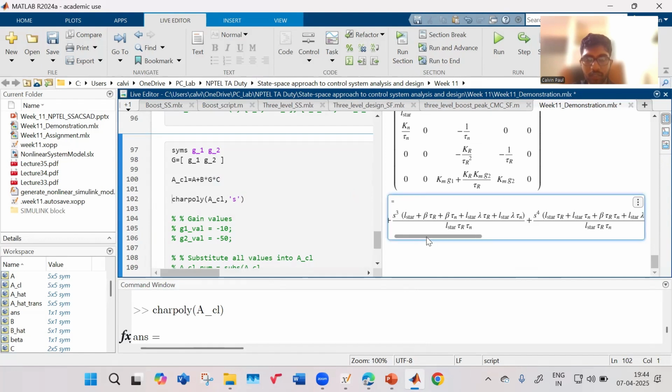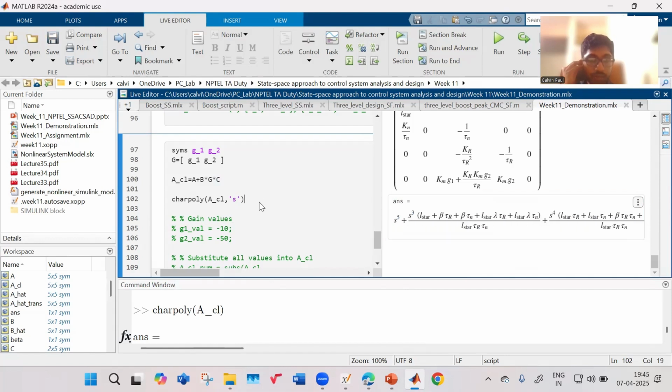It comes out as s^5 plus s^3 plus s^4 minus s plus s squared. So the characteristic polynomial comes out in this form. Okay, so what can be changed? You'll observe G2 can change s, and G1 can change s, and s squared also can be changed. And this also can be changed. But there is very little scope of varying all the poles. All the coefficients of the characteristic polynomial cannot be changed by this way of output feedback. That is a limitation which we have.